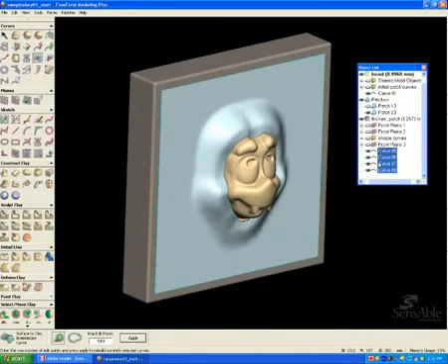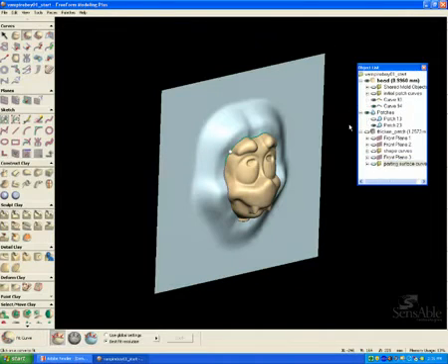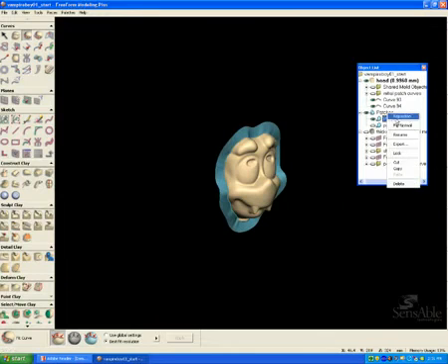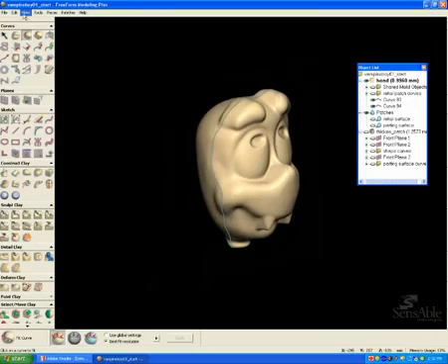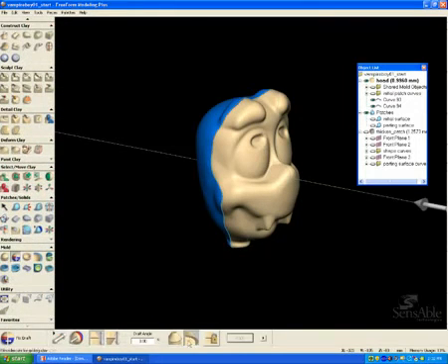and I'm using clay to patch intersection to get a new parting line. It's going to be very similar to the initial parting line that I created, but since it is a little different, I want to make sure it's perfectly accurate, so I just create a new parting line. And like I said, it's very similar, but it's a lot more accurate than the first one that I was using as a guide. So right now I'm just going to go ahead and use the Fix Draft tool again, since like I said, the parting line is a little different.